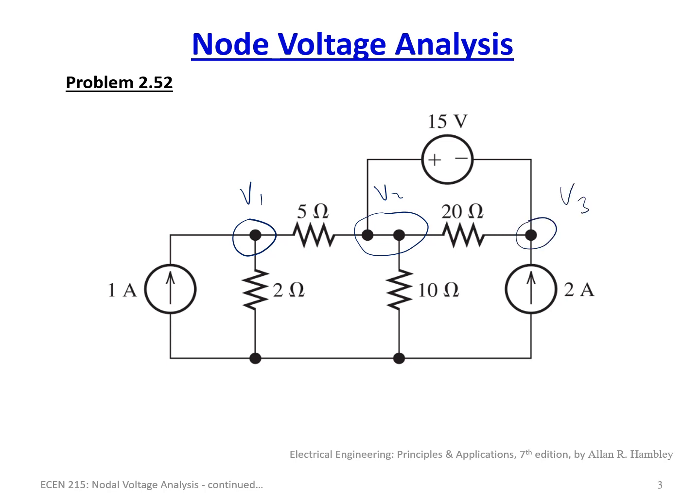I've seen students write an equation for this, or V2, and then write an equation for this separately. You don't need to do that. This is all shorted together. This is all one node because it's all about the elements that are connected together. This 5 ohm resistor is connected here, and this 20 ohm resistor is connected here, and it's all connected to this one node.